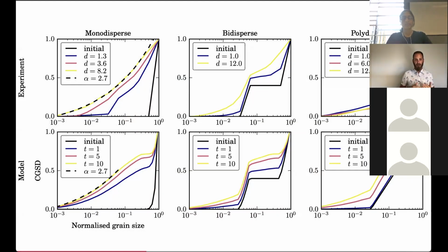And so when you have crushing and mixing, we actually end up with very different sizes in the material. We get lots more crushing happening as these particles are... So the particles originally we crush until there's one large particle surrounded by lots of small particles. But then as we start to shear, we mix them up again and the large particles find each other and then they start to crush. And so these kind of simple models now capture this behavior quite nicely.